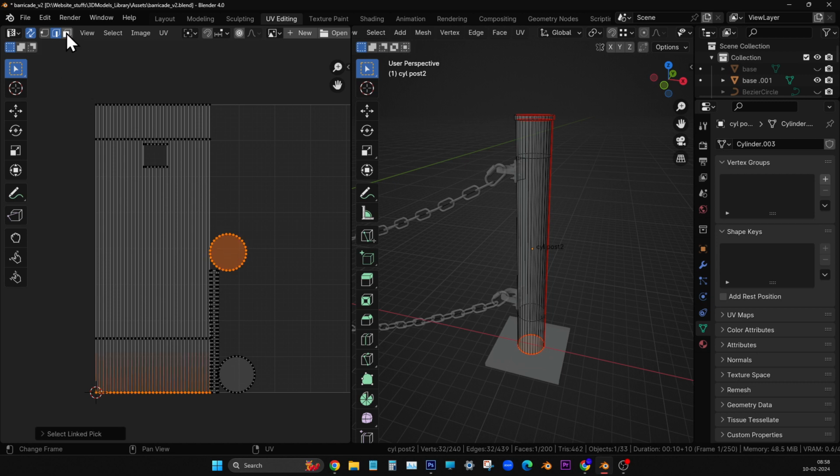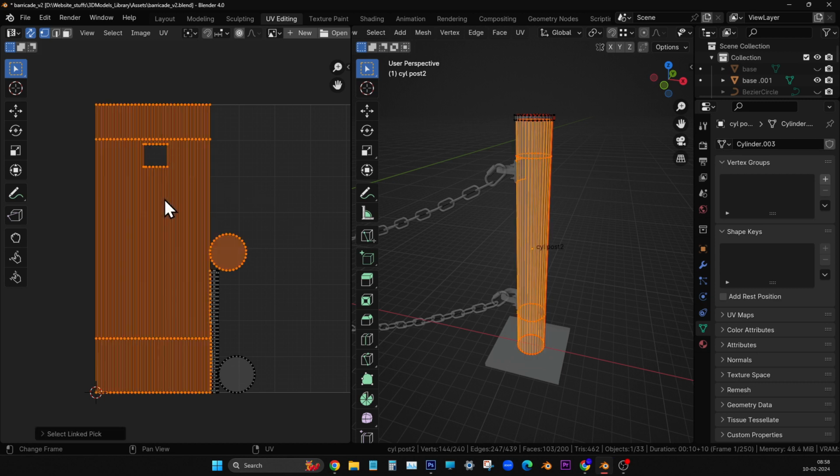And I should make sure that whenever I'm selecting the islands, I should always be in face mode. This is the thumb rule. I should be in face mode and then only I should choose the islands. If I'm in vertex mode, you see how it is getting selected. I'll keep the cursor on one island. Other things also will get selected when I am in vertex mode.